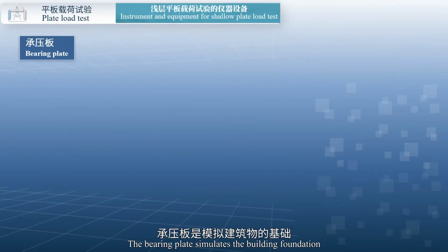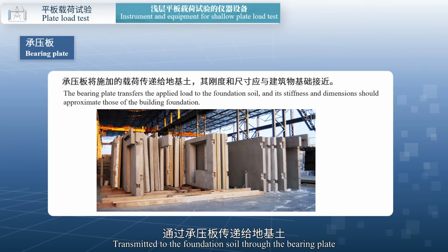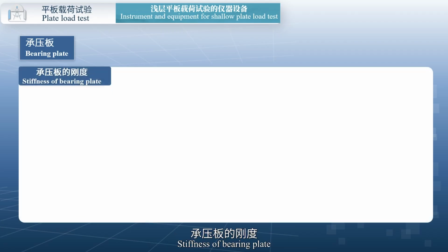The bearing plate simulates the building foundation. Apply the load transmitted to the foundation soil through the bearing plate. Its stiffness and dimensions should approximate the building foundation. Below, let us understand the stiffness and dimensions of the bearing plate. First, stiffness of the bearing plate.